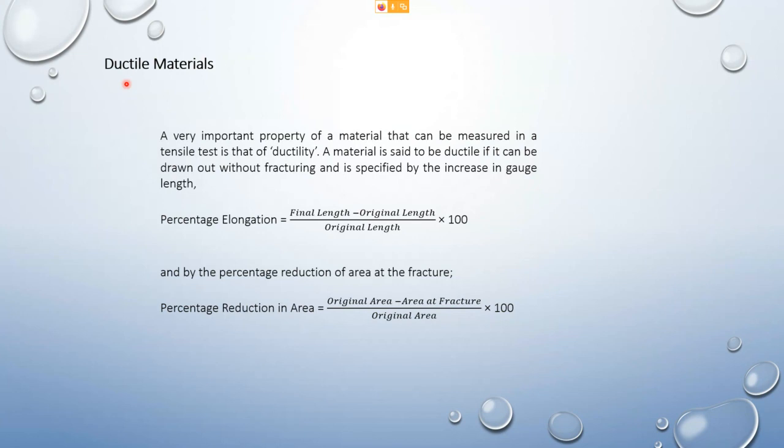It cannot be stretched out in length. Even with a slight increase in length, the material will break. That is brittle. Usually brittle materials that fail under tension show a crystalline fracture, while ductile materials show a fibrous fracture.